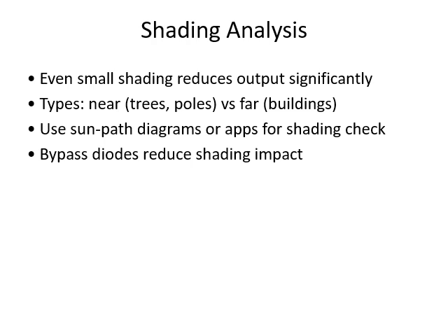The thing is, there are small photovoltaic cells all arranged in an array to create the overall photovoltaic panel, right? So if one cell is shaded, then it won't be producing any current. Instead, it will act as a hot spot because it will start to get heated. So that can be another concern, particularly when there is shade on even a small area.